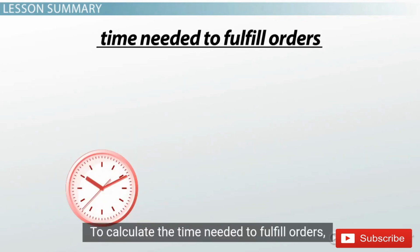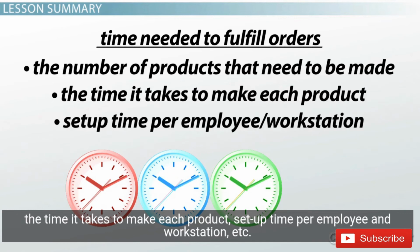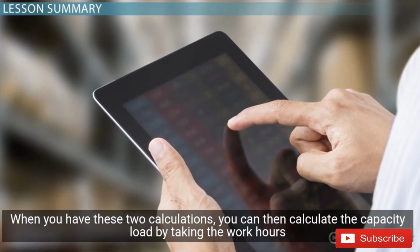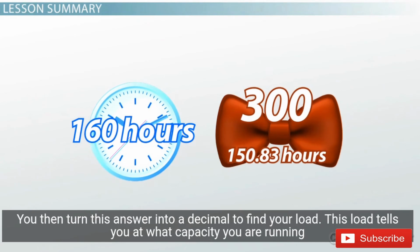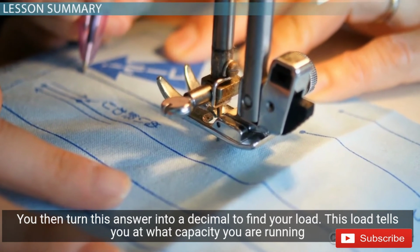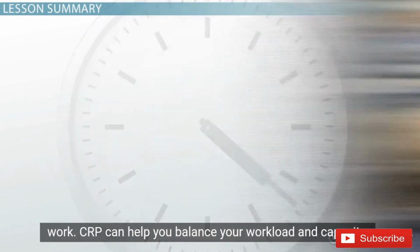To calculate the time needed to fulfill orders, you need to know information such as the number of products that need to be made, the time it takes to make each product, setup time per employee and workstation, etc. When you have these two calculations, you can then calculate the capacity load by taking the work hours needed to fulfill orders and dividing it by the number of available hours. You then turn this answer into a decimal to find your load. This load tells you at what capacity you are running. Anything over 100% is over capacity and means you do not have enough hours available to do all the work.